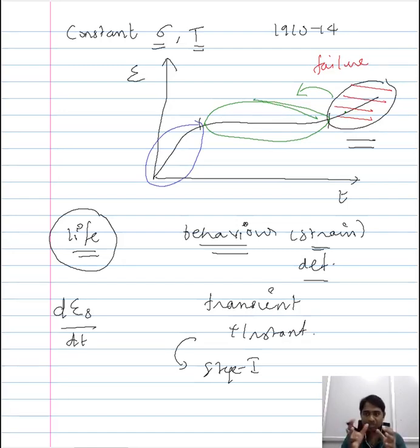And now, based on the other sections of the curve that we have, particularly stage 1, we understand the deformation that the material would exhibit within the application, the deformation that is unavoidable when you use the particular material in an application. And secondly, from the duration the material spends in the steady state condition, we will be able to estimate the life of the material in a given application. So this is what we do in creep testing.